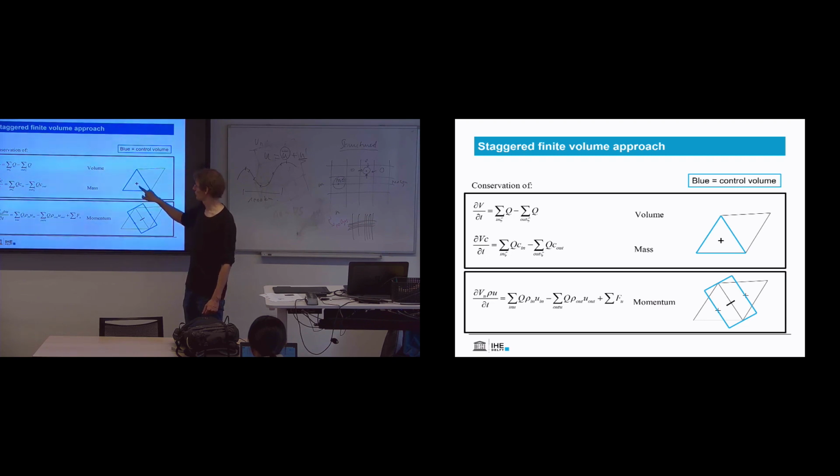And it's all centered on the cell center position. Yeah? That's the ortho center of the geometry of the grid. But for the velocities, we have a somewhat slightly different control volume over which we calculate the velocity changes.